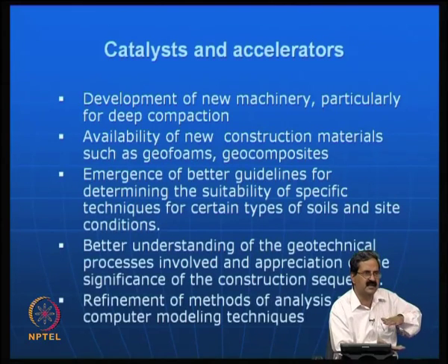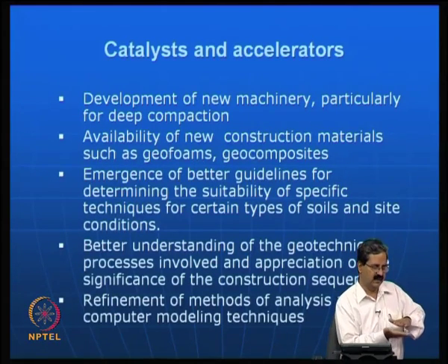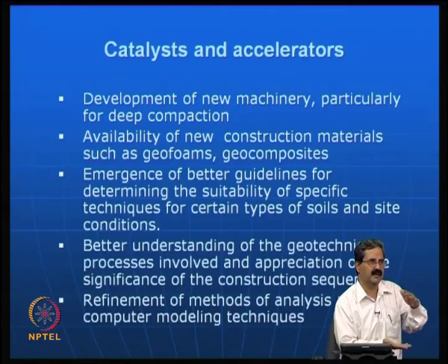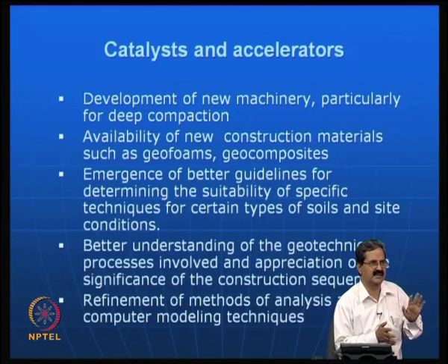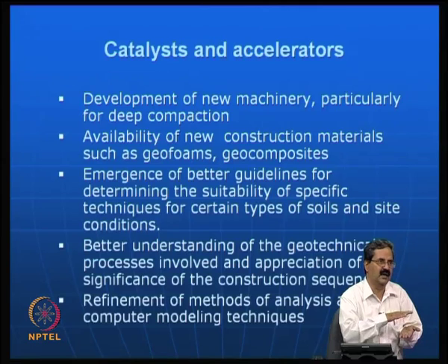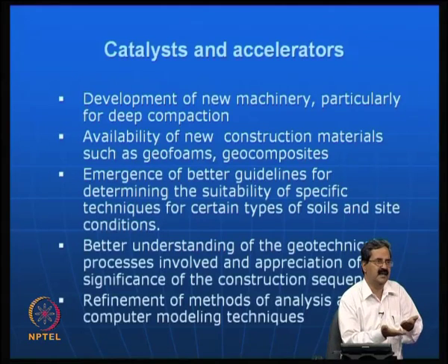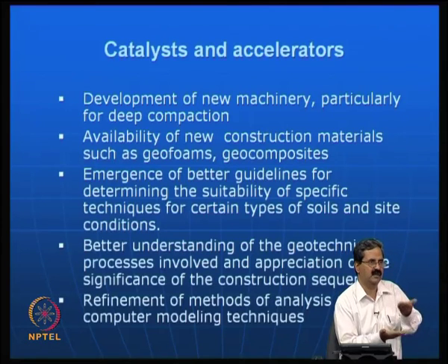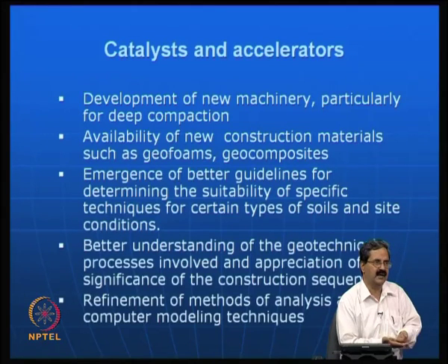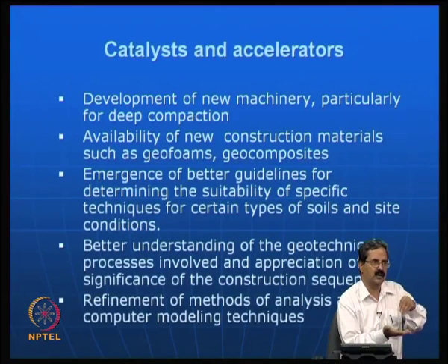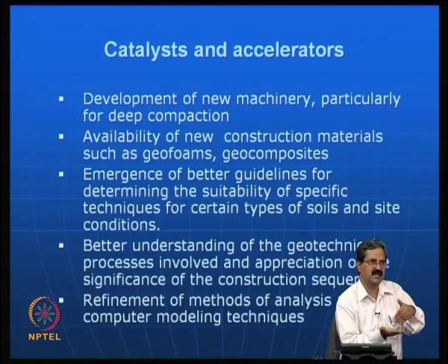What is the subgrade? Why are you constructing different layers? Essentially, we are constructing the road to see that the traffic load is taken care of, right. The only thing is, the existing load is some traffic loading, and you are trying to provide some material which can take care of the load, nothing else. All this concept of sublayers is just an older concept. In the sense, of course, the concept is important, as the purpose there is to distribute the load gradually. You have a subgrade, a subbase, a base, and a wearing course. Whatever load comes on the wearing course has to be distributed, and when you calculate the load reaching the subgrade, that should be less than the bearing capacity of the subgrade.